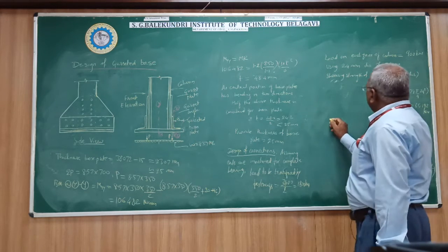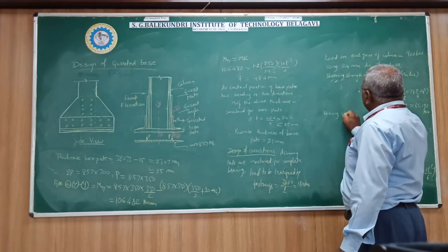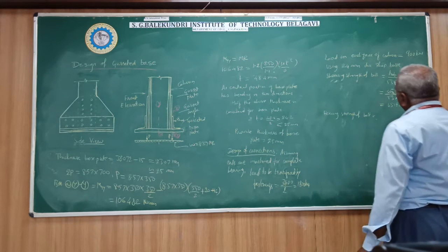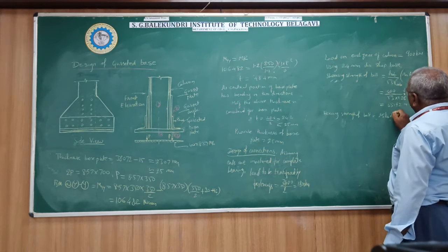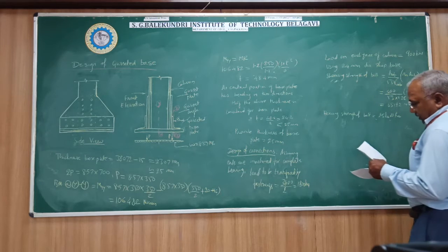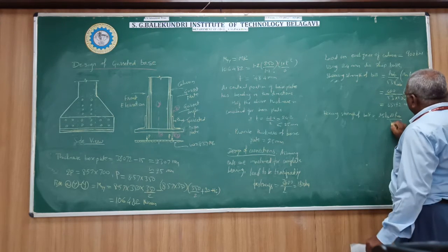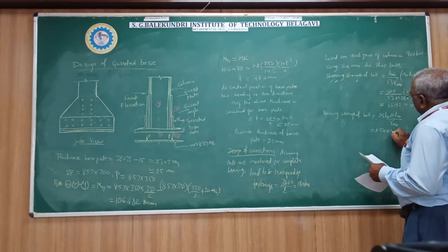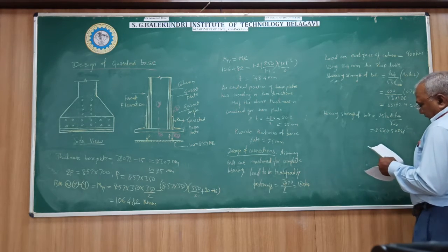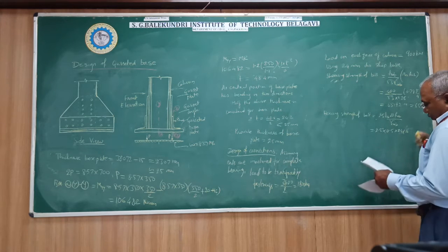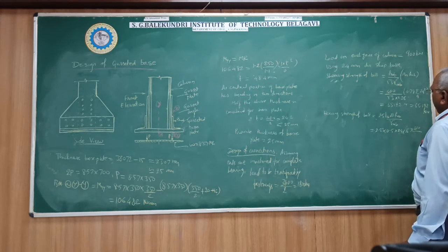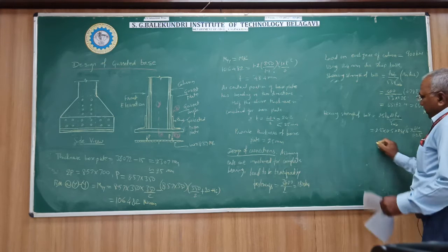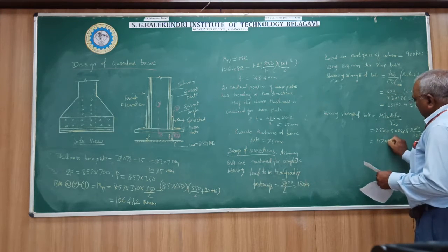Now the bearing strength of the bolt equal to 2.5 kb into d into t into fub, divided by gamma mb. So this is equal to 2.5, kb is taken as 0.5, d is the 24 mm diameter bolt, t is the thickness of the gusset plate 16 mm, into fu 410, the ultimate stress in the steel, divided by 1.25. So it is 157.44 kilonewton.